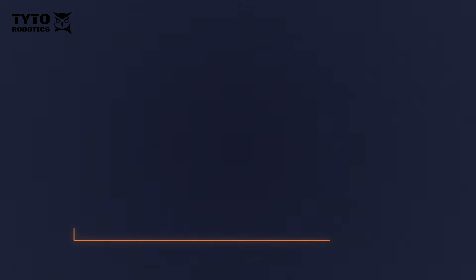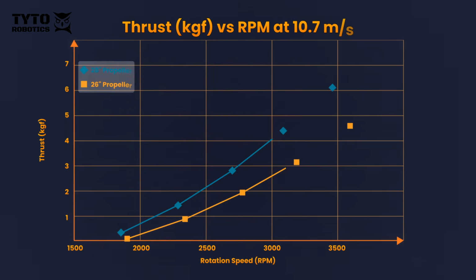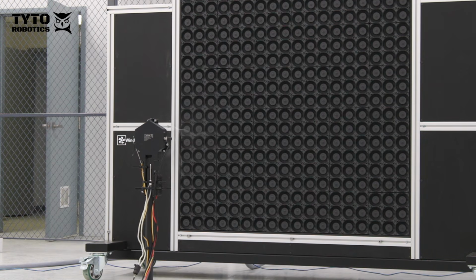Alright, now that I have the data, let's see what's happening. We performed a step test at constant wind speed with the flight stand, and each data point represents a recording from a different throttle point. As expected, the 28-inch prop is generating more thrust at all the throttle points, even with the wind blowing. Let's skip ahead to the results at maximum wind speed, 17 meters per second.